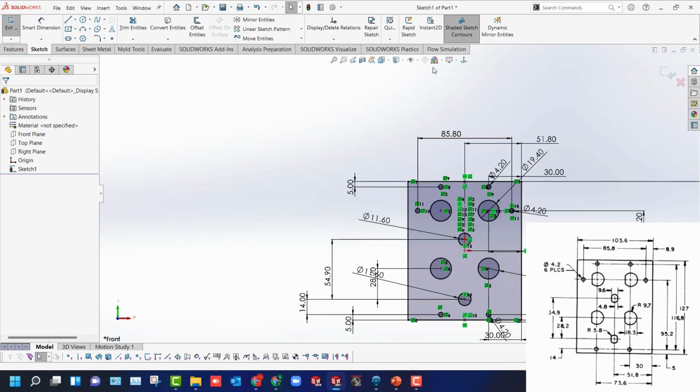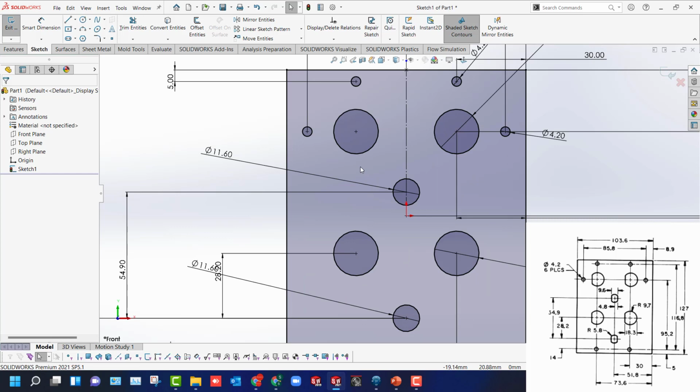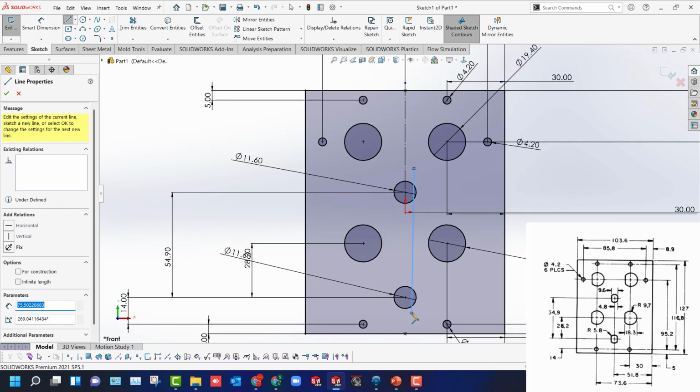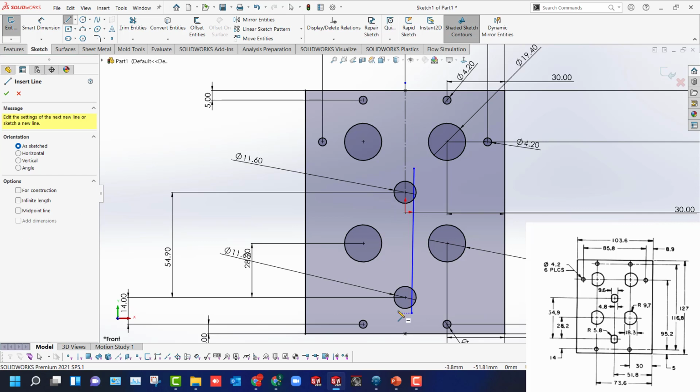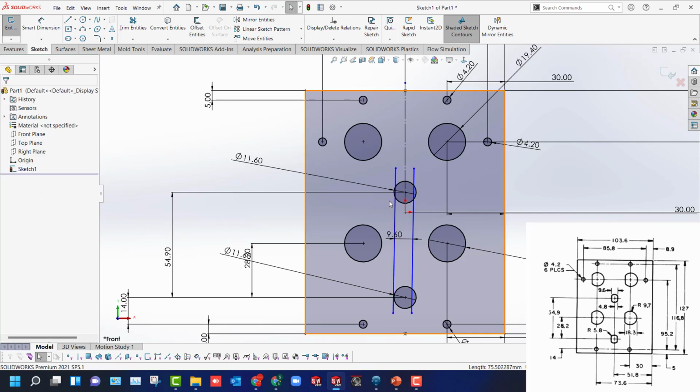That's fine. So I think we have fully defined the sketch, but still a few more things are needed. We can simply remove all the geometry constraints, and now we can go ahead with the line so that you can create this cutout vertical one. Even you need to create the same cutout for the center circles, so that also we can do. So from here to here it is okay. The line should be vertical. What I can do is I can use the offset, right? So the offset distance between these two is 9.6 actually. You mentioned the same.